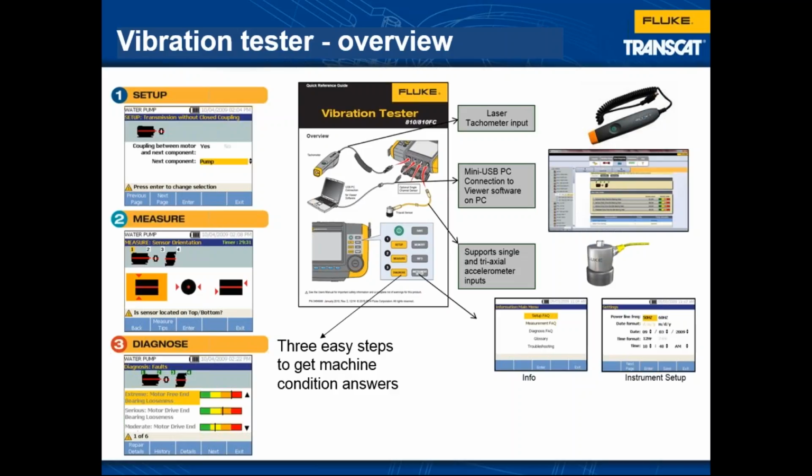Think of setup like the questions your doctor asks when you go in. The doctor asks you, where does it hurt and when does it hurt? Same kind of thing. We're going to tell it some basic information about our machine. Then we're going to take measurements with a triaxial sensor. You can see the triaxial sensor over on the right. And then this tester is going to compare data to a database of hundreds of thousands of machines that are taken from real rotating machines, just like your machines.